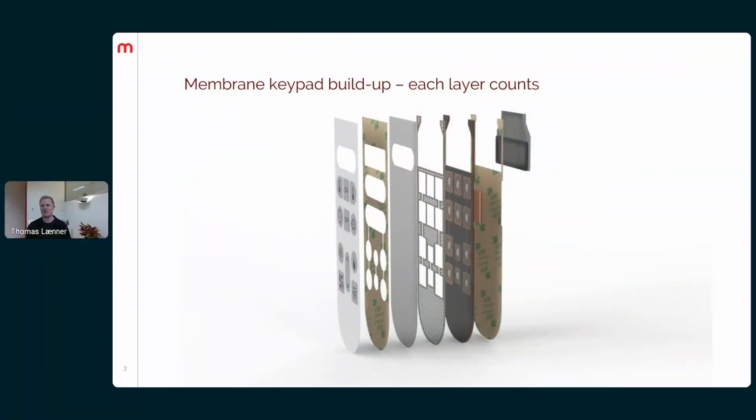As you can see here, a membrane keypad is built up like a sandwich. With this webinar, we want to give you a look at the possibilities you can choose between and the most relevant materials early in the development process. This might save you time spent on redesign later in the process. This webinar is also structured around these different layers.